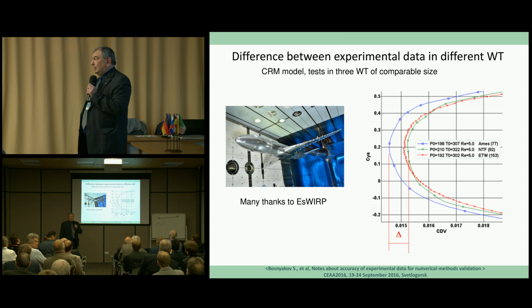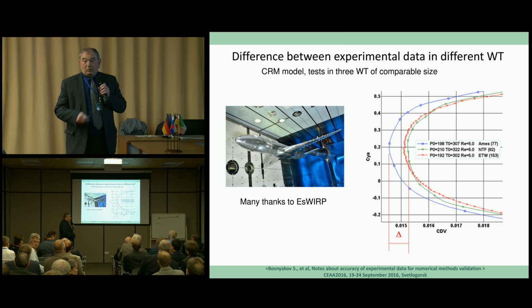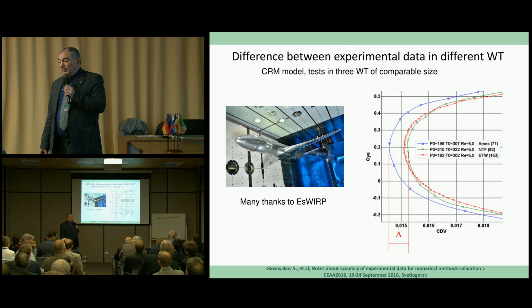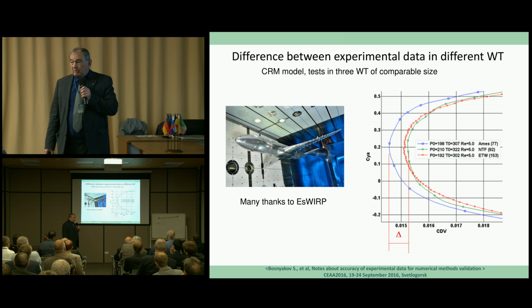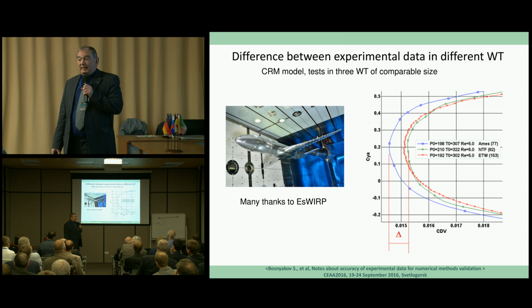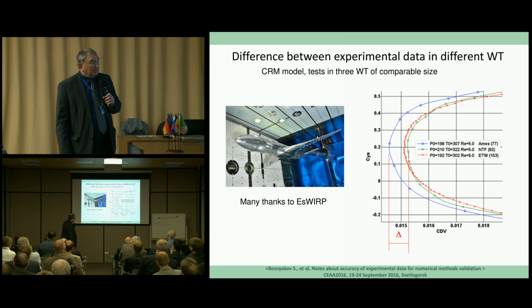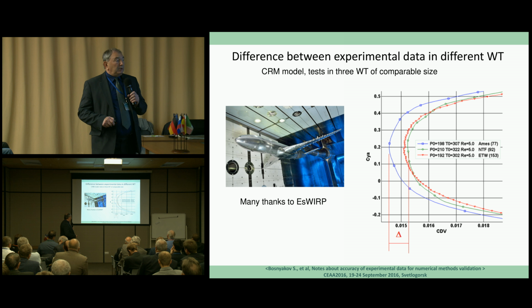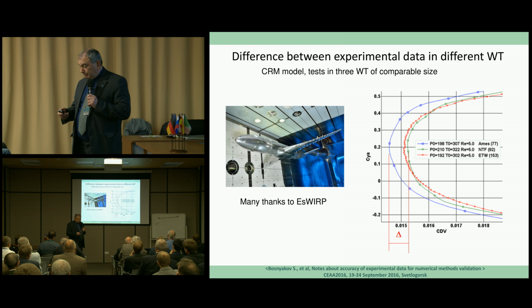The dispersion is also typical for wind tunnel test results. I found data for the well-known Common Research Model, CRM, and these data are from very respectable test rigs. It's the National Transonic Facility, the NASA 12x12 wind tunnel, and also the European Transonic. It is easy to see that the range or dispersion is quite severe, and what's to do?